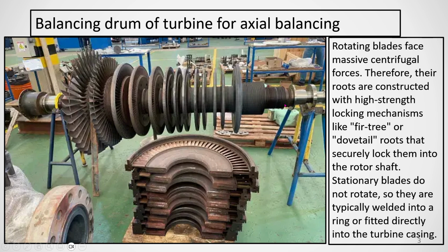To balance this, you see the diameter of the rotor here and the diameter of the rotor here are different. Steam comes through the nozzle to both sides, and the pressure will be the same. But as this area is less and this area is more, the high pressure steam will act on the additional excess area and balance the low pressure rotor's tendency to move to this side.